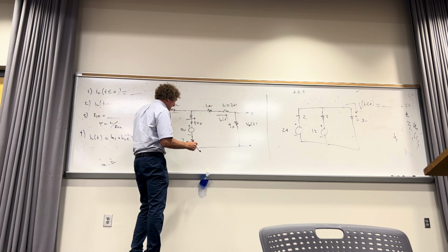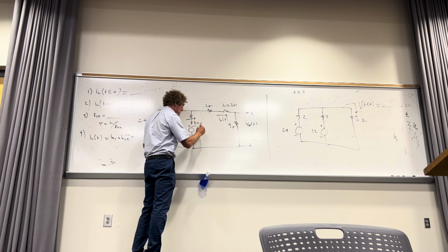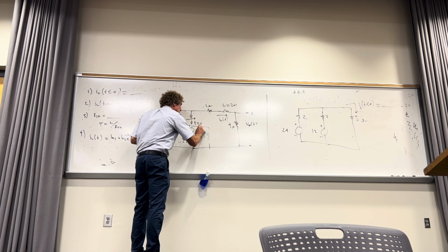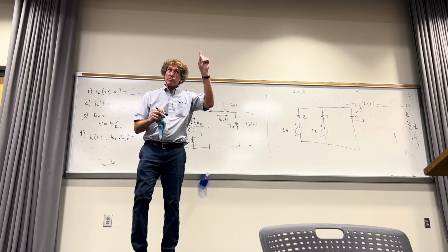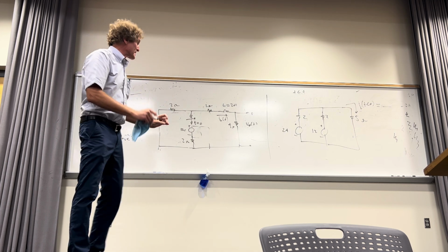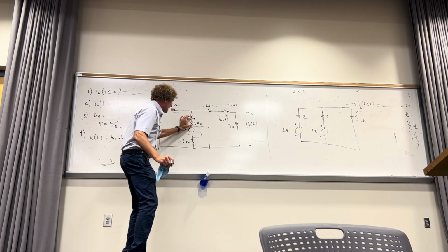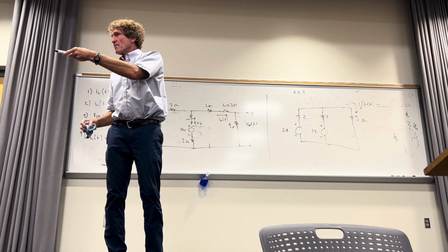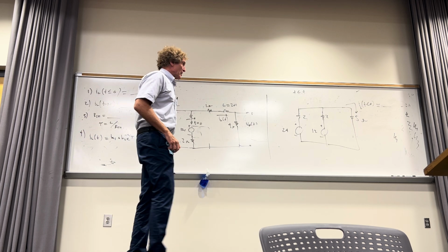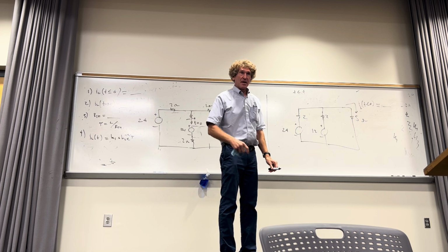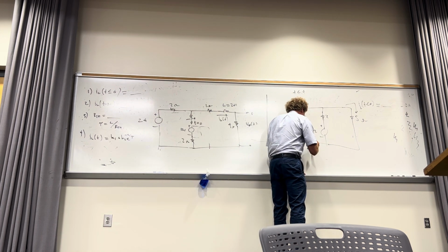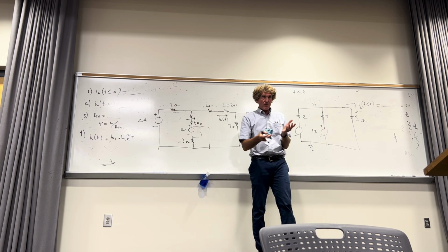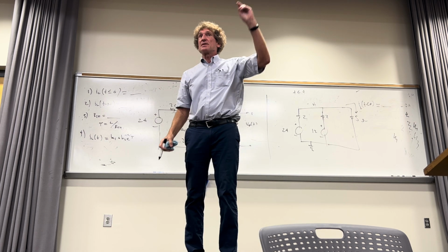Now, I want to say this. You can't do that if there's complexity, like if there's a resistor here and then another resistor here. You can't do that. But here, it's 2 series components. As long as the plus stays on top, I don't care if I slide this down here and slide this up here. It has the same effect. Make sure you see that. We good with that, class? Over here, you all with me? Okay? Now, I'm going to show you a trick. Yes, you're right. We can ground this, and we can find V1 there, or just V, and then we can solve that with nodal or mesh. How many see that?